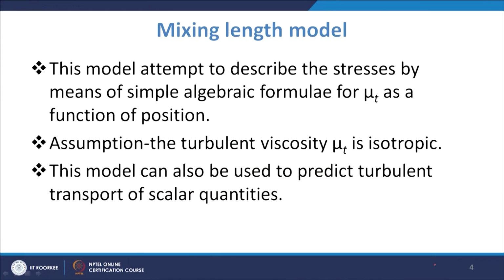Now, if we talk about the mixing length model, in this lecture we are going to get some idea about how the mixing length model works, and how we use it for the prediction of the turbulent stress components. This model attempts to describe the stresses by means of a simple algebraic formula for mu t as a function of the position, and the assumption is that the turbulent viscosity mu t is isotropic, and it can be used to predict the turbulent transport of scalar quantities.